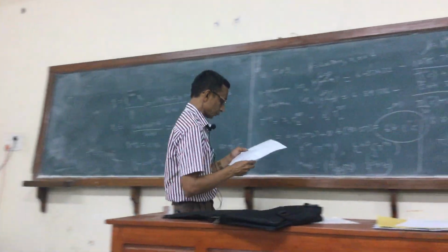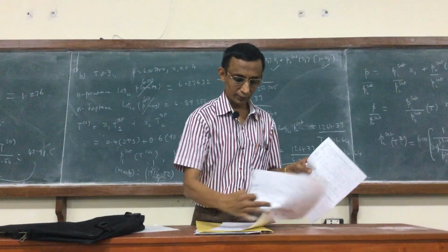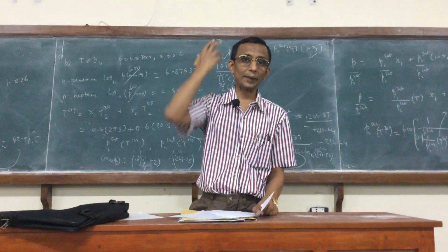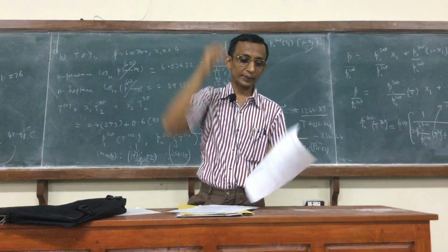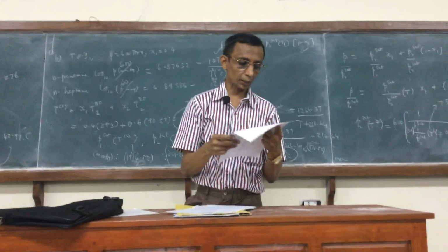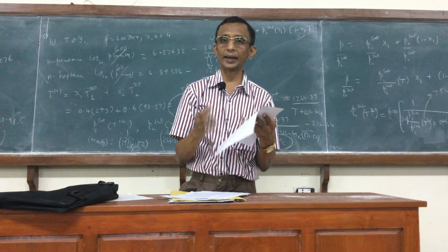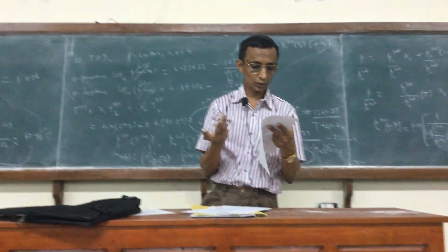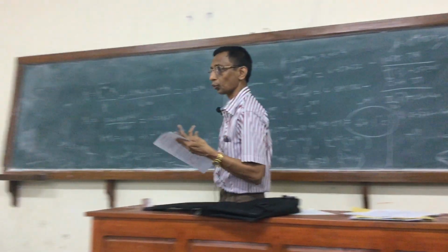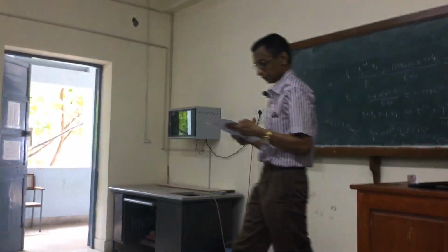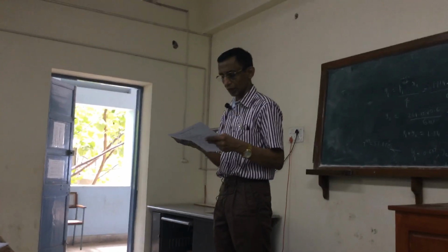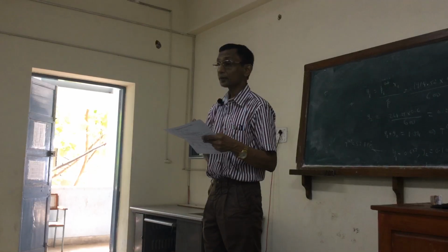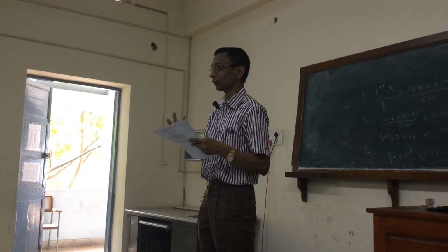So what I am going to take is problem A, because the point to note with the modified Raoult's law is what are the parameters that we have to determine. Suppose you choose the van Laar model, it has two parameters A and B. Or if you choose the three-suffix Margules model, you have two parameters A12 and A21. Some books use A and B for the three-suffix Margules model also, probably from Sandler. So the question is, how are you going to determine the parameters?